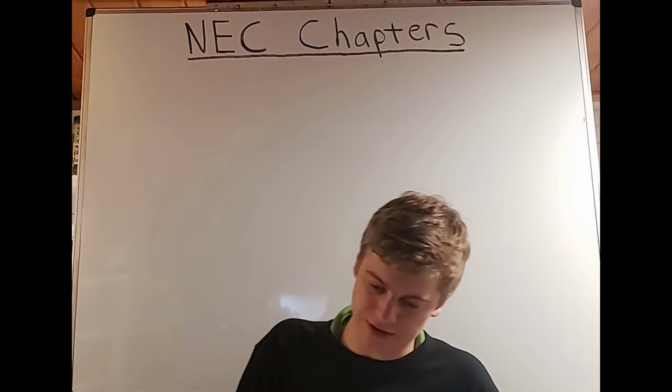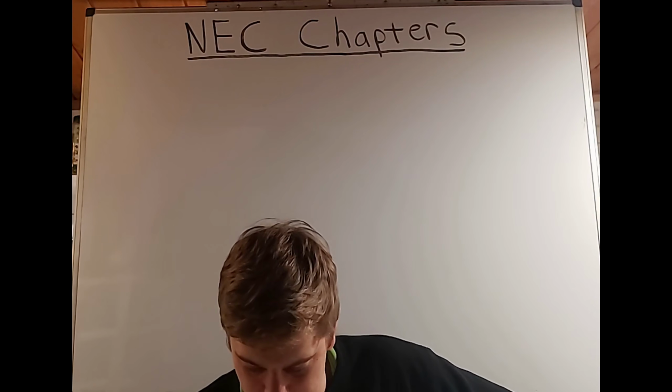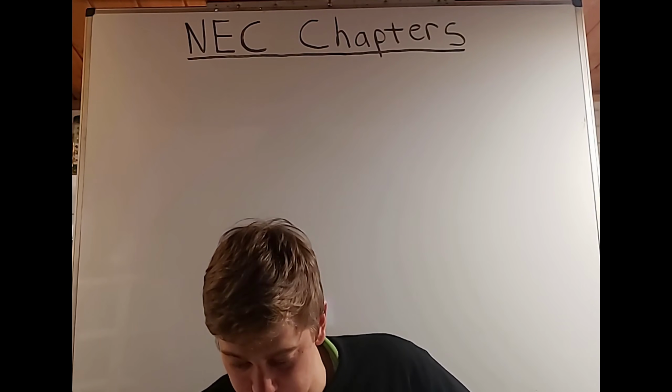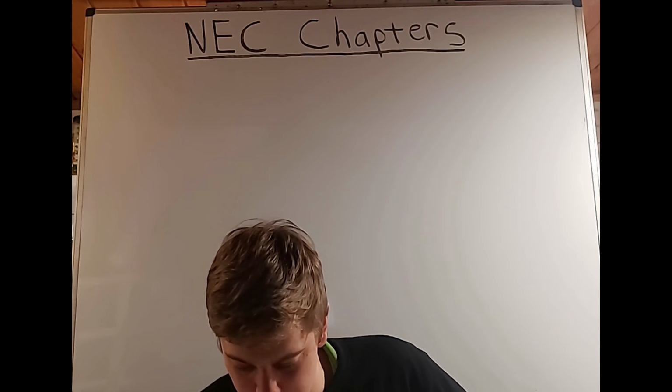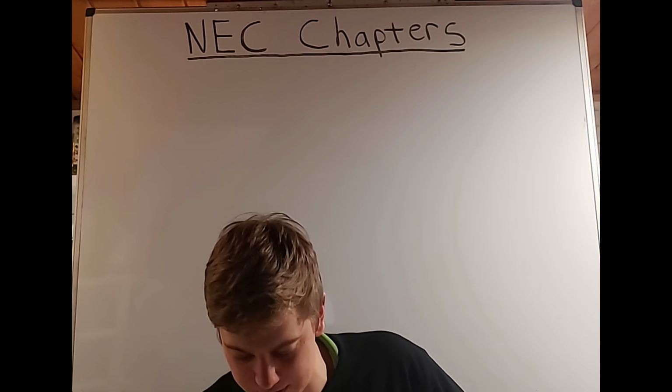Okay, but here's very important, number 2, ceiling outlets. Boxes shall be required to support a luminaire weighing a minimum of 50 pounds. A luminaire that weighs more than 50 pounds shall be supported independently of the outlet box.